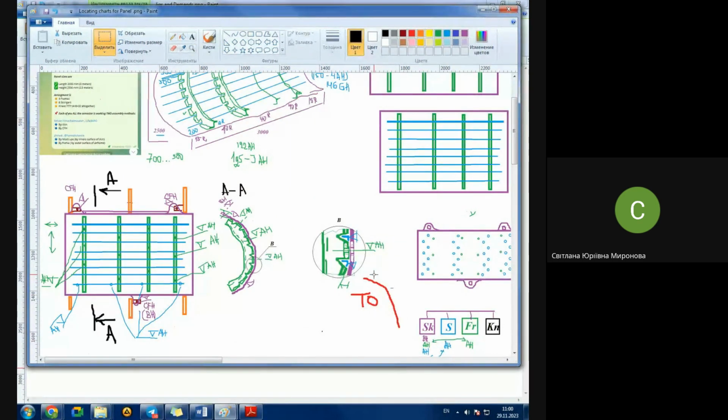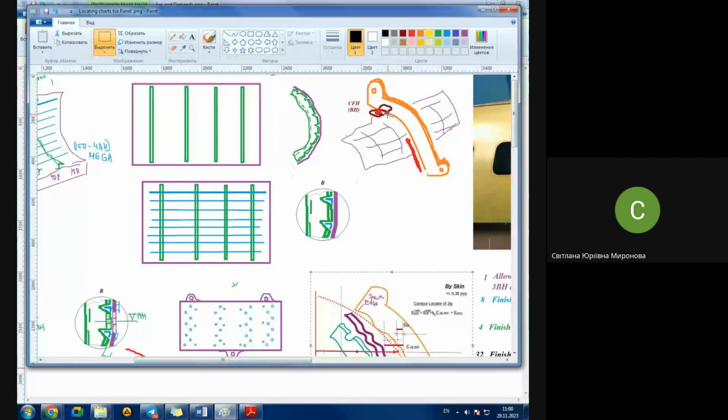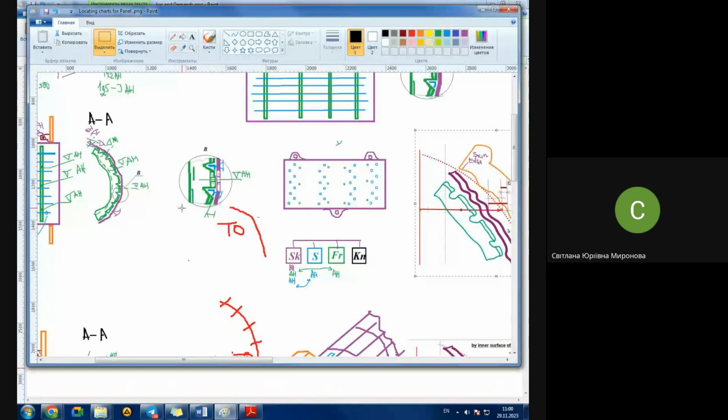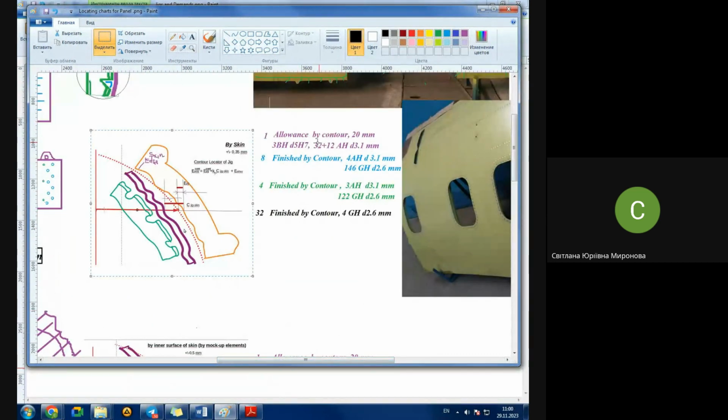Interchangeable elements, the most important, are theoretical outlines of those locators, inner theoretical outline. And also it has base holes. So we suppose to say the theoretical outline with accuracy and base holes. Base holes we even mentioned here, and the accuracy also mentioned here. Where? Base holes, diameter 5, H7.